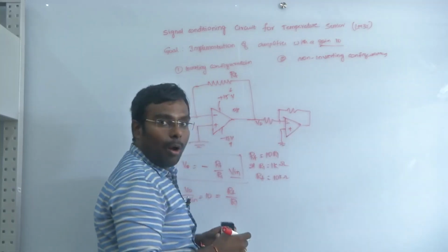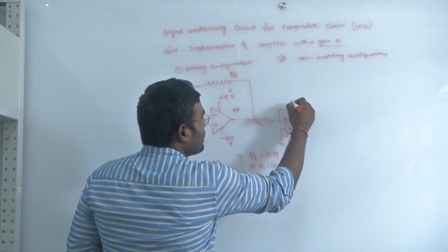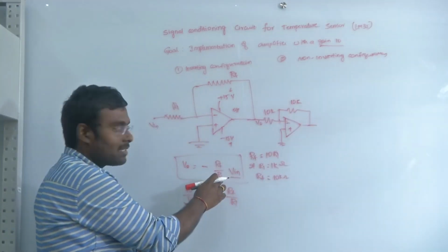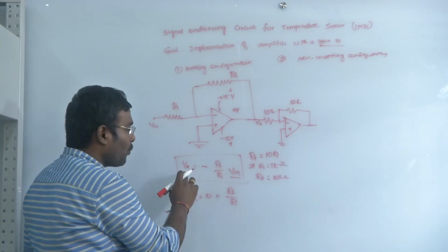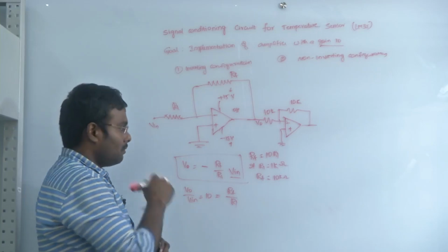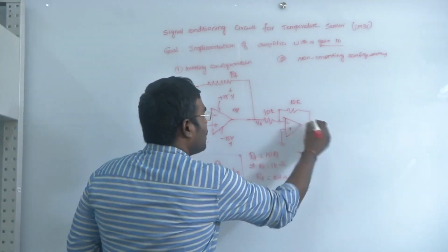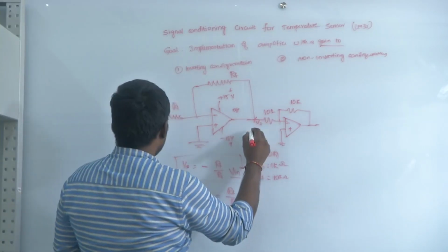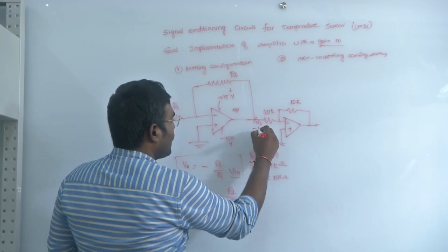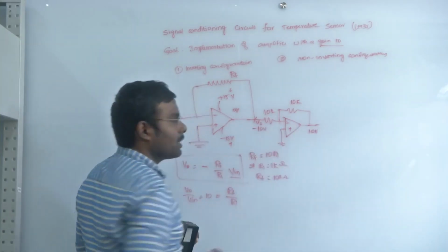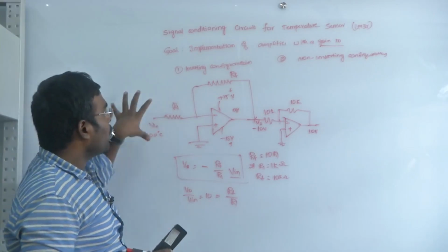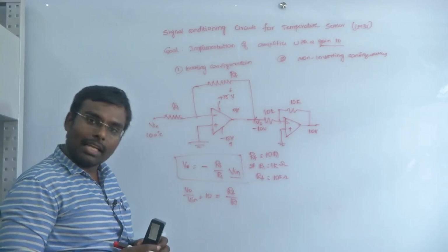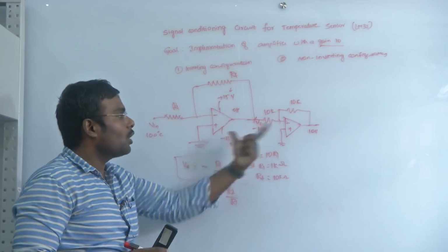the same inverting operational amplifier. So in this case I will take 1K, 1K. So now if both RF and R1 are the same resistance, we will get RF by R1 as 1. So V0 will follow Vin. As a result, for 100 degrees centigrade, if this is giving minus 10 volt, here we will get an output of 10 volt. So we could achieve 10 volts for 100 degrees, but this is by using the inverting operational amplifier configuration. So we will be using two operational amplifiers.